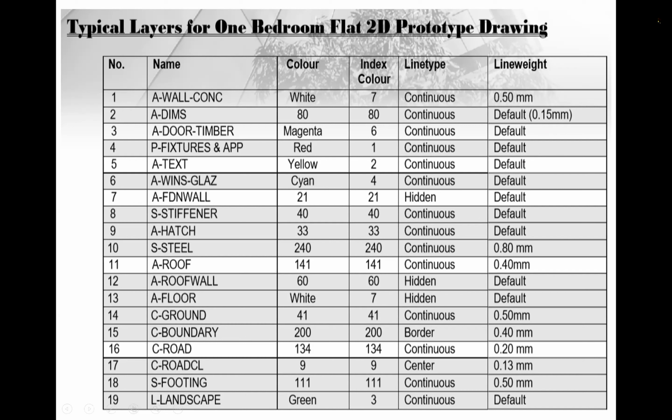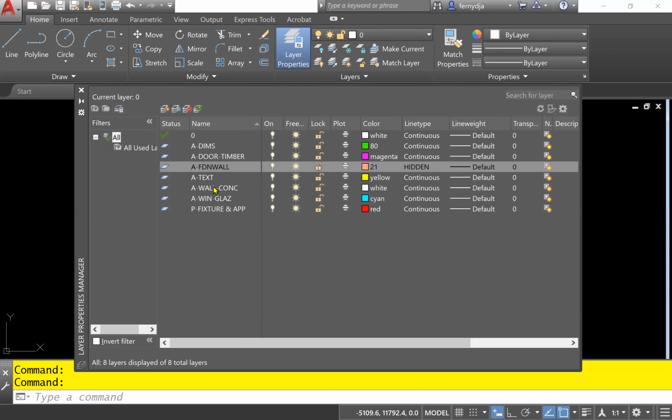Now the line weight default is not changed from the screen that we're on. So we're going to wait until we finish changing the line weight, then we will come out of it, and then we'll look at how you change the line weight default. So let's just look at how you change the line weight for the wall layer first, which needs to be 0.5. So I'm going to go back to my drawing screen at this time. All right. And pick up the line weight. So for the wall layer, I'm selecting the wall layer. I'm going to change the line weight default to 0.5.